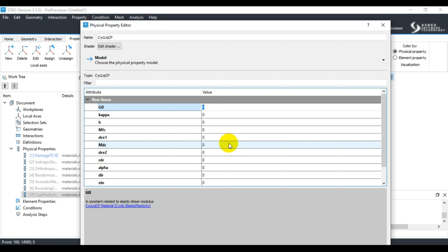For material behavior control, it is used to control and account for the effect of gravity and static loads initially. The material behavior is set to linear elastic to simulate the initial response of the material to these loads. After the initial stage, the material behavior is updated to achieve the desired elastic-plastic stress-strain response, allowing for more accurate representation of the material behavior under cyclic loading conditions.